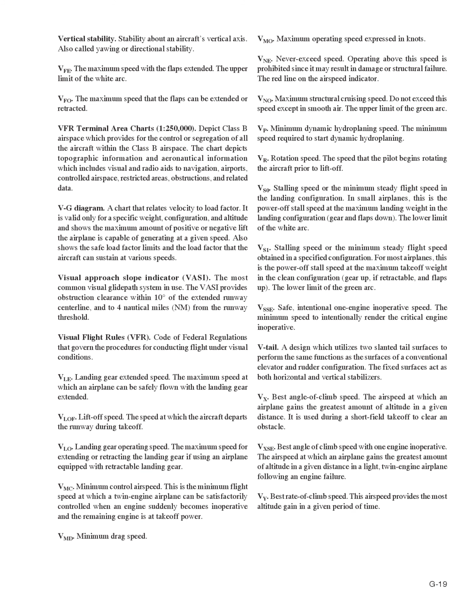VR. Rotation Speed. The speed that the pilot begins rotating the aircraft prior to liftoff. VS0. Stalling speed or the minimum steady flight speed in the landing configuration. In small airplanes, this is the power-off stall speed at the maximum landing weight in the landing configuration, gear and flaps down. The lower limit of the white arc.